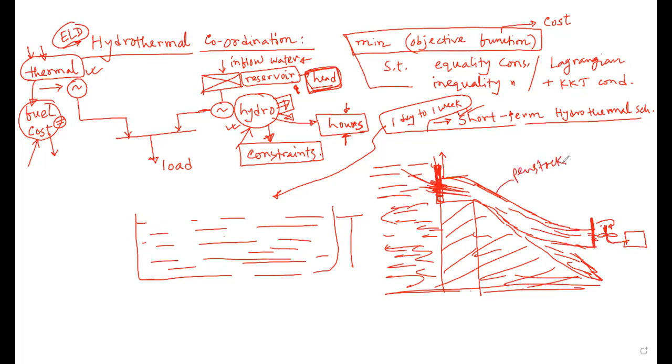This is of course a very short view of the hydropower plant. Once the turbine starts to rotate, the unused water goes out in this direction. And this is your generator, so you step up using a three-phase transformer, and you transmit the power. So this is, in short, the structure of hydropower generation. What I was saying is the height; this is the head, the available height of the water level in your reservoir.